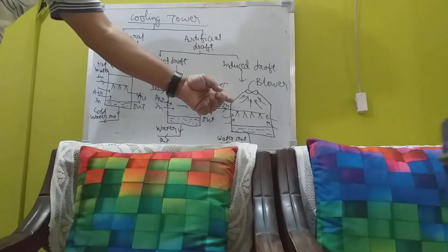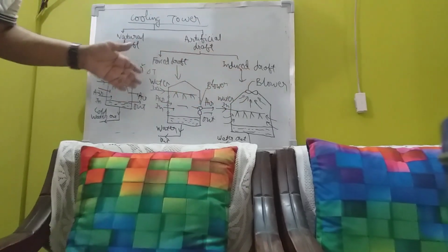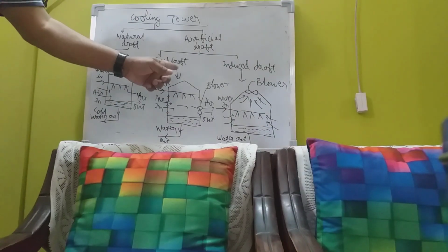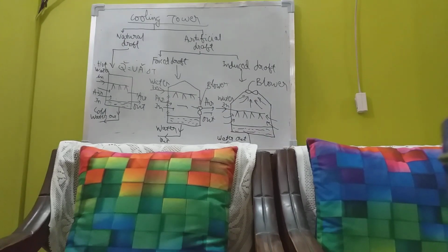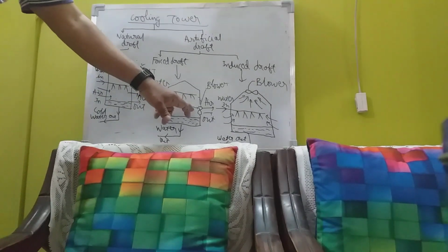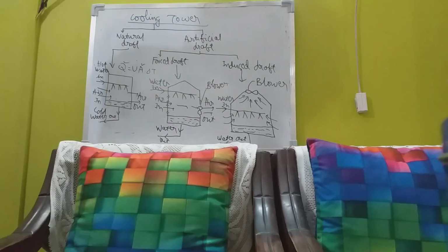Air in, air out. So there should be sufficient distance from any obstacle. It means clear space should be there to a large extent in the cooling tower, in case of this type of forced draft cooling tower. This is a disadvantage of this type of cooling tower, because in present-day urbanized atmosphere, in places like Delhi, Mumbai, etc., where the congestion is too much, you don't get a space. And because you don't get space, it's very difficult to get a side space.